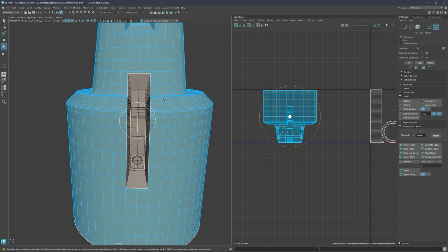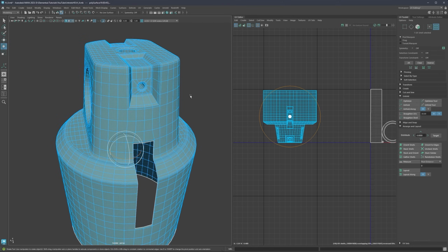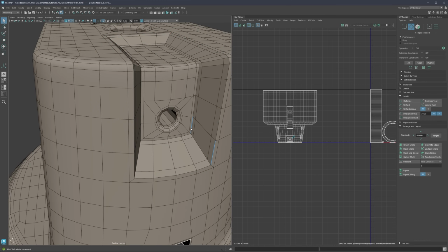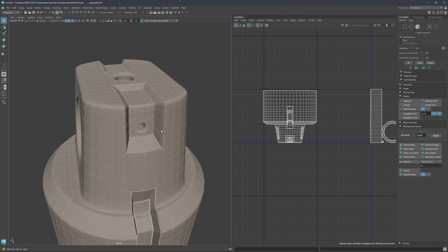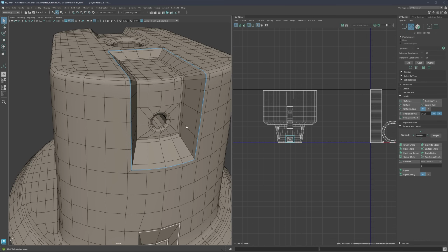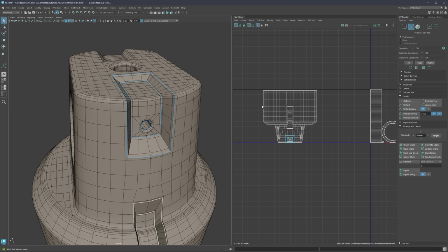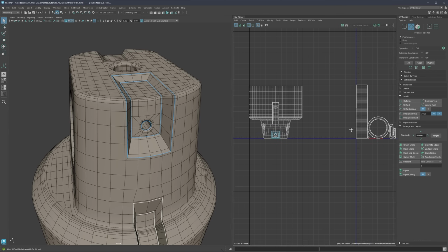All right, so now that we have that, let's see what else is left. We're going to continue with the same procedure. Here is going to be our next depth. Here is going to be the next one. Let me select all of this. Here's going to be one, here's going to be another, and here is going to be the third one. We can select all of them at the same time and simply go and create cut.